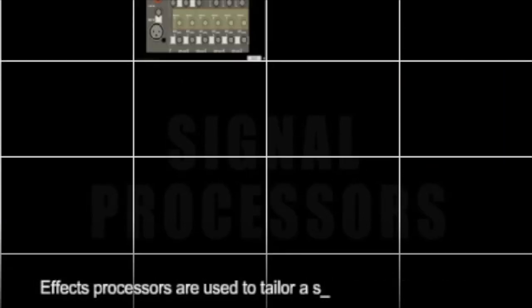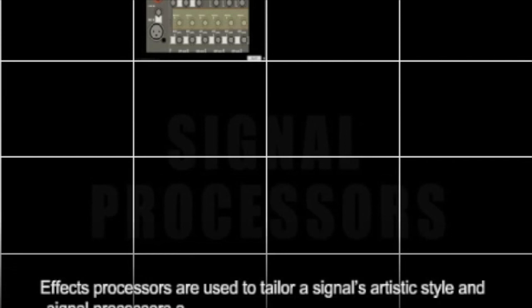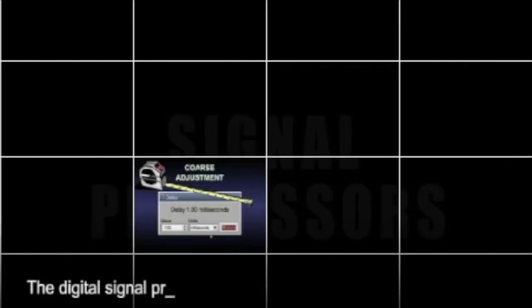Effects processors are used to tailor a signal's artistic style, and signal processors are used for overall system adjustment and loudspeaker management. Dynamic processors are used to affect the dynamic range of a signal and include compressors, limiters, noise gates, and expanders. Frequency processors include equalizers and bandpass filters and are used for tuning the audio system. Time processors provide critical time alignment for systems with multiple loudspeakers as well as finite alignment between devices. The digital signal processor is paving the way for ease of operation, monitoring, and control of audio system devices.